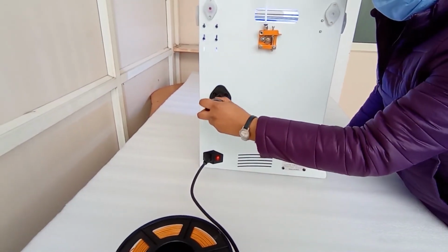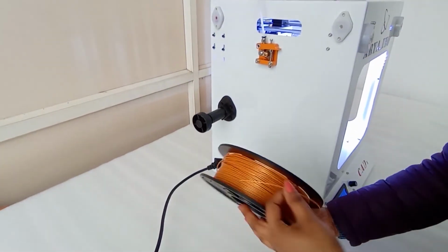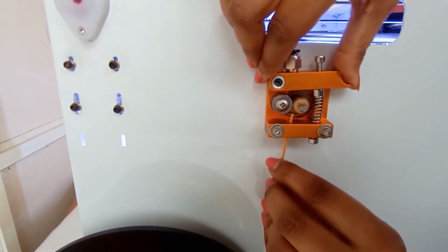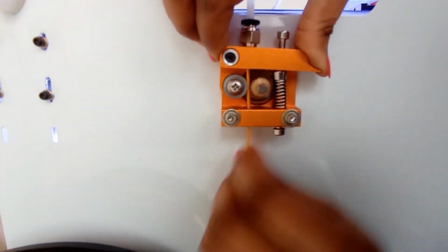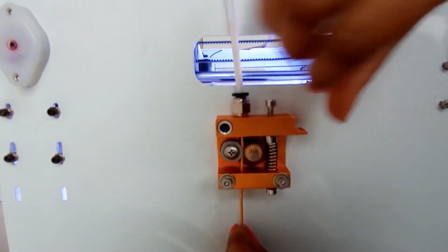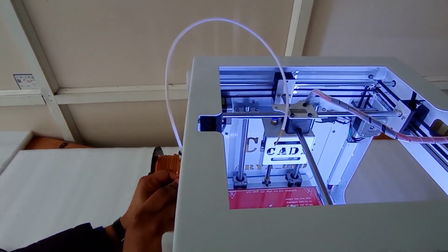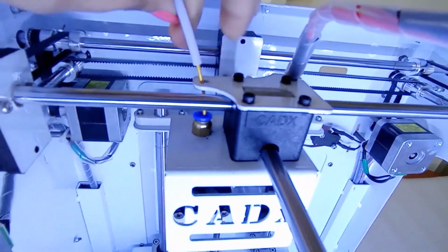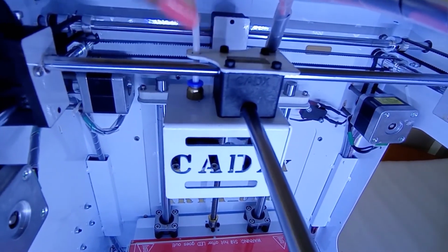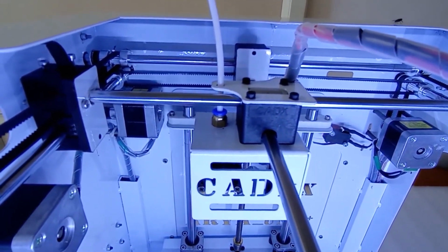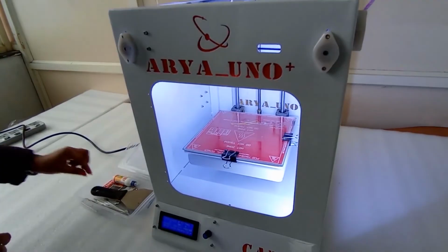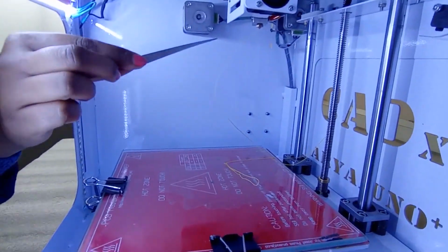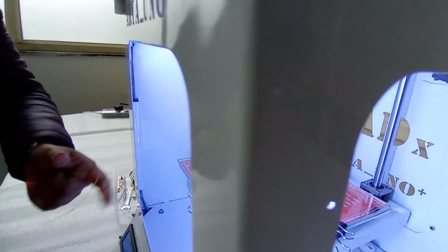And it's done. How do you insert PLA in a 3D printer? Connect the filament holder to the 3D printer. Hang the PLA on the filament holder. Now press the extruder downwards and pass the PLA through the two holes while pressing the extruder. Now the PLA will pass through the pipe. Insert the filament into the nozzle inlet. Push the tube inside the hot end till the end point and press gently till the material starts to come out from the nozzle, as shown. So now your 3D printer is ready to print any object.